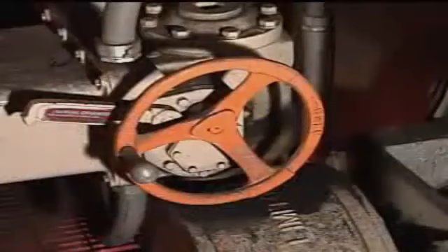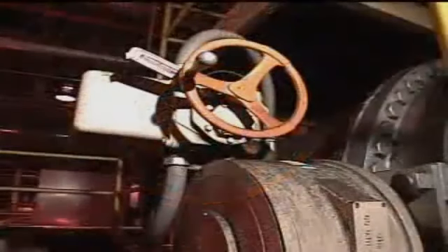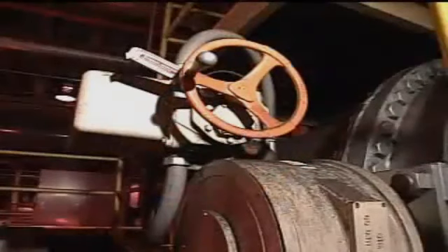In addition to expansion joints, the piping in a circulating water system typically includes a number of valves. For example, many circulating water systems use motor-operated butterfly valves as pump discharge valves. This type of valve is open when the pump is operating, but closed if the pump isn't operating to prevent any backflow through the pump.